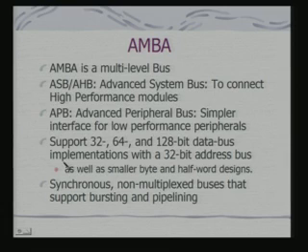In fact, the whole bus supports what is called 32-bit, 64-bit as well as 128-bit data bus transfers, okay, fine, using a 32-bit address bus, and this is the basic characteristic of ARM. It can also be used for doing smaller transfers like word, half word, byte, etc. It is a synchronous, non-multiplexed bus that supports burst mode transfer, as well as pipelining.